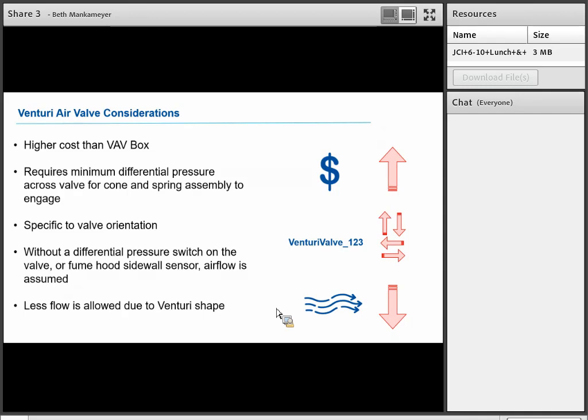They go up to 3 inches, but if you get out of that pressure range, then the Venturi valve will go out of calibration because it's not going to be calibrated for anything outside that range. So what that means is it doesn't just drop right off of calibration, but you're going to be outside of that guaranteed 5% range.